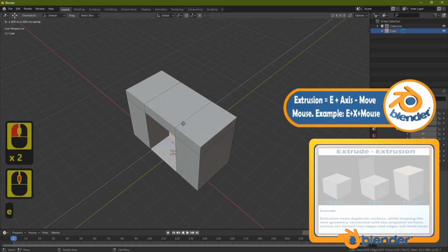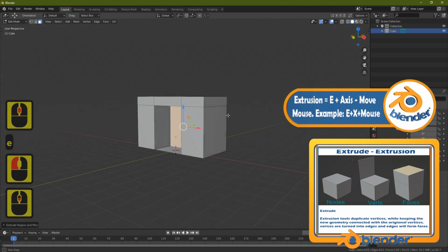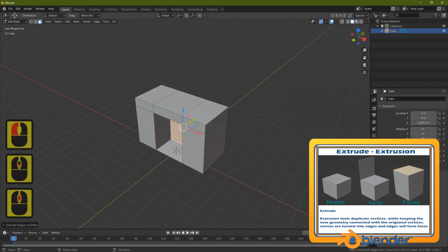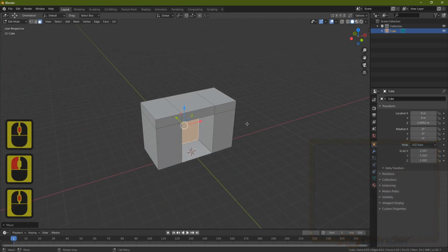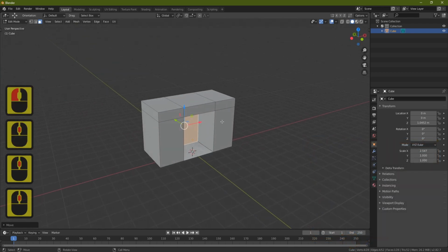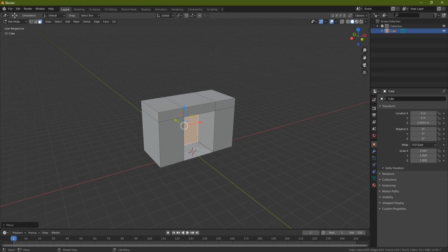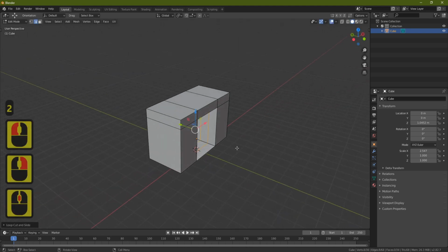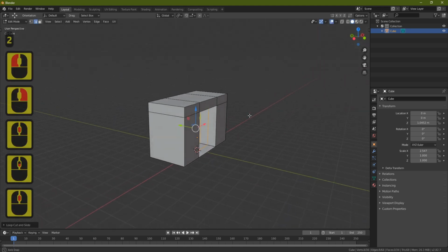to pull it back down to about there, something like that, maybe a little bit further actually, because we want 2 doorways going in here, and we're not going to be doing the inside of the saloon, but we need to make it look as though they're going actually somewhere. Now what we're going to do is press Ctrl R and put it down here just so it follows around on the inside of here. You can see here that it's going around the inside. 2 again, left click, right click, and now we're going to make the opening for these doors here.